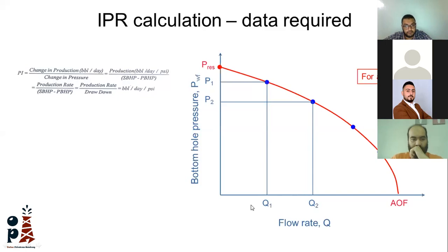In an actual case in my company, there is a well that you cannot exceed 600 or 700 psi drawdown, or you will have some sand production. So we did our best to control it from the surface, to have some choke and increase the wellhead pressure, so we don't have a drawdown greater than 400 psi as a safety factor.